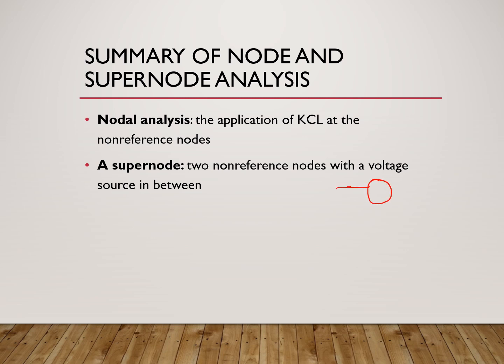When you have a voltage source between two non-reference nodes, and if there is some resistance or some element in parallel to it, that can also be ignored. So this V1 and V2, this voltage source, these terminals plus this resistance wholly form the supernode. You are going to be ignoring this when we are writing KCL, but we'll write a KVL.